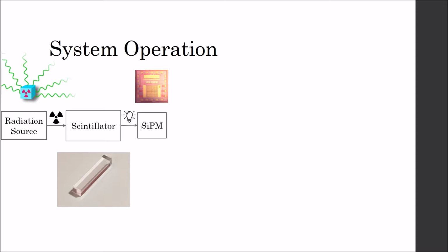The silicon photomultiplier is the first step into the control circuit. It's a small chip with a small window at the top. It receives the photons emitted by the scintillator and through breakdown events creates current pulses which are sent to the control circuit. The chip design is limited to 1024 photons received at a given instant, and each breakdown event only lasts about 10 nanoseconds, creating sharp current pulses. Using this specific silicon photomultiplier is the goal of the design, as it is cheaper than the alternatives on the market. Once sent into the circuit, the current pulses need to be conditioned before they can be analyzed.